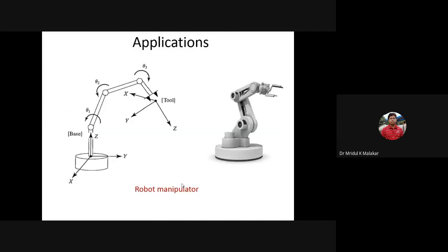Okay, so now some applications, like the robot manipulator. See how complex these things are. If you see that one hinge is there, another one is there, another one is there, but if you see that structure, it is non-linear. It depends on this one, this one depends on this one. So every time theta 1, theta 2, theta 3 are three angles, and it can move in the xyz coordinate. Again there is another motor, an xy base. So this is a robot manipulator.